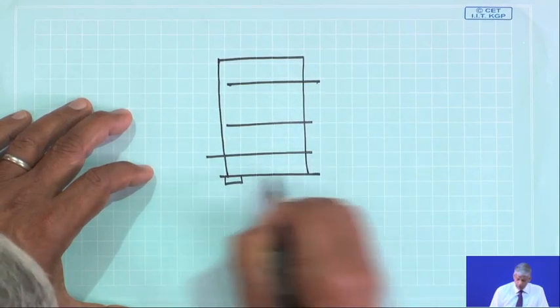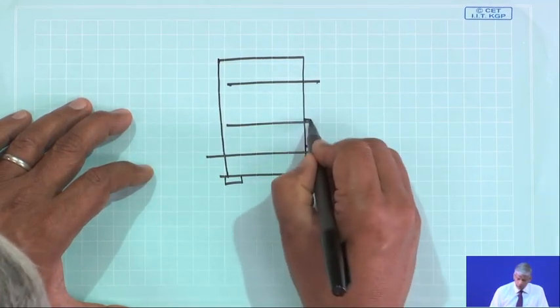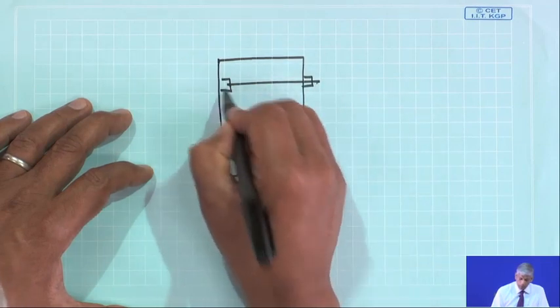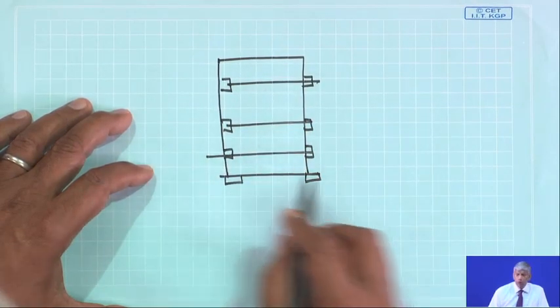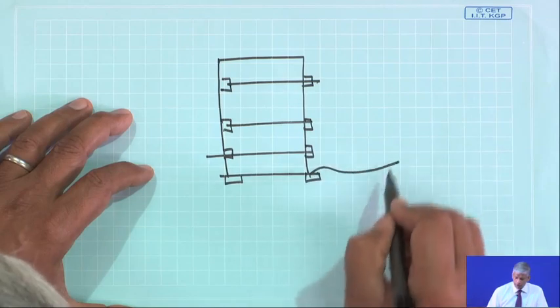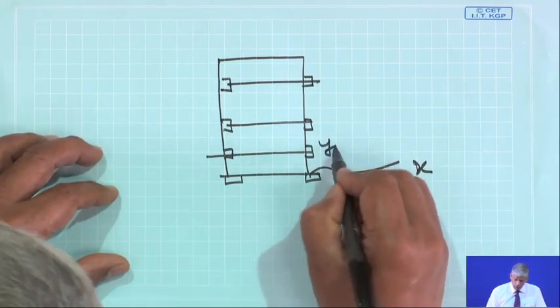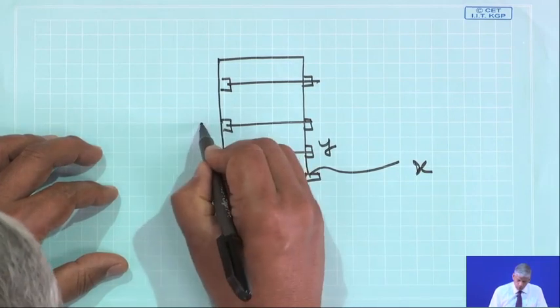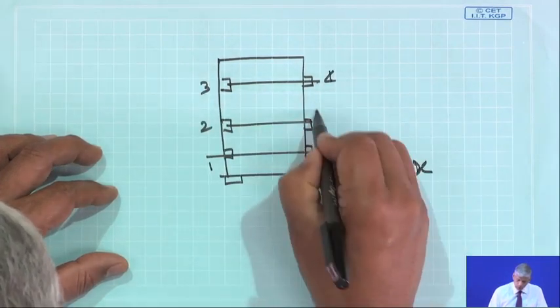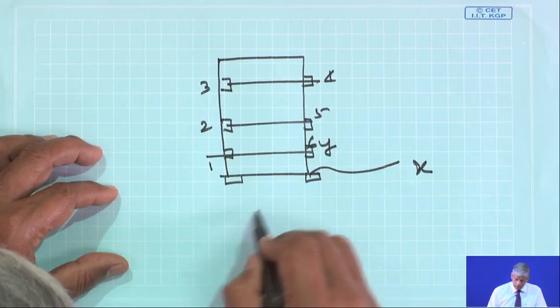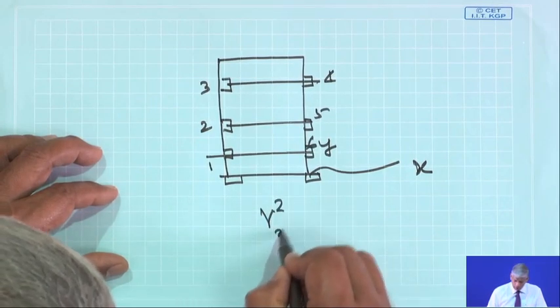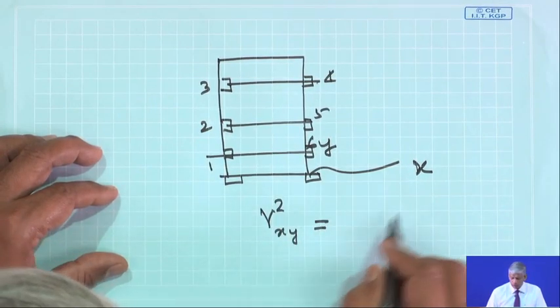Well, the access to you is the bearing locations. So, all you do with a common point of vibration x, you can measure the roving y at locations 1, 2, 3, 4, 5, 6 and find out the coherence gamma square xy between these signals.